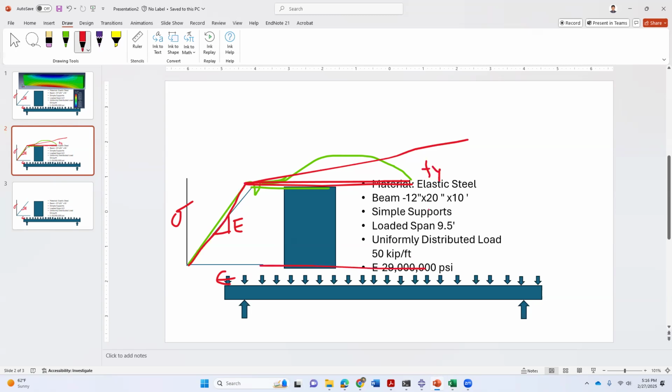So this failure strain, where the steel will just tear up, will be like 0.2 or 0.1, whatever. I think I assumed 0.2, 20% strain. So this will be our elastic plastic region. Once an element hits this elastic strain, depending on the modulus of elasticity and the stress here. If it's a 60 grade steel, that means my yield stress is 60 KSI, right? In US terms. So in MPa, it will be 415 megapascal, I believe.